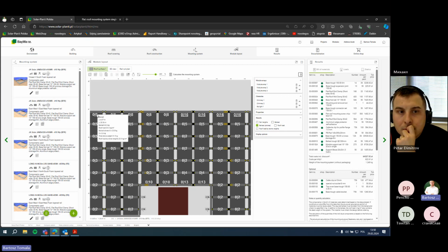3.5 kilo. That's why it's calculated like this, because the program tries to make as close as possible to minimum required ballast. And as you can see, now we have the total weight stone 31.5, and it gives us 23.9 kilos per square meter, and minimum ballast calculated was 30.5, so we have 1 kilo more.